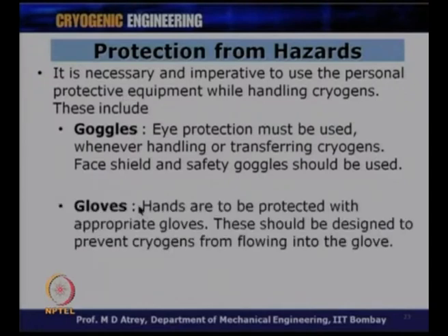Similarly, gloves, for your hands. Hands are to be protected with appropriate gloves, not normal gloves. There are gloves available for handling nitrogen. These should be designed to prevent cryogens from flowing into the gloves. So, it should ensure that liquid nitrogen doesn't enter your gloves. It should prevent cryogens from flowing into the gloves.